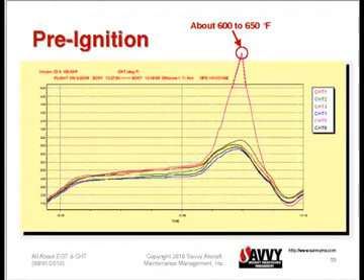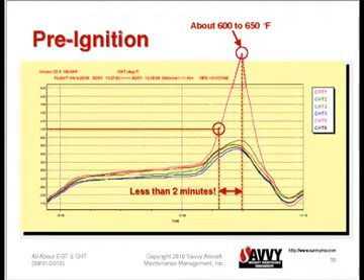And the reason it went almost cold was, well, I'll show you the next slide. But at any rate, I want to impress upon you just how rapidly an event like this occurred. The pilot applied takeoff power here. About a minute and a half later, the CHT on number 1 passed 400 degrees Fahrenheit, and hopefully he got an alarm at that point, but obviously didn't do anything about it.